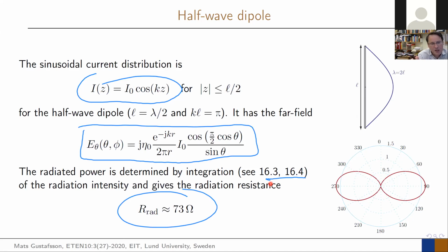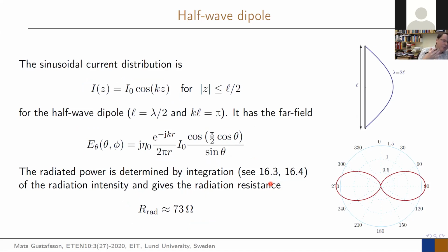People have tried to do it, but it's not of huge interest to have it more accurate, because as you saw before, your dipole is not even a half-wave dipole. It is slightly below. But it has a radiation resistance of the order of 70 to 75 ohms. That's where it sits, a little bit above 70 ohms, which is not too far away from 70 ohms. So it will not work terribly with a 50 ohm cable. You would need a balun, which can also change these values when added.